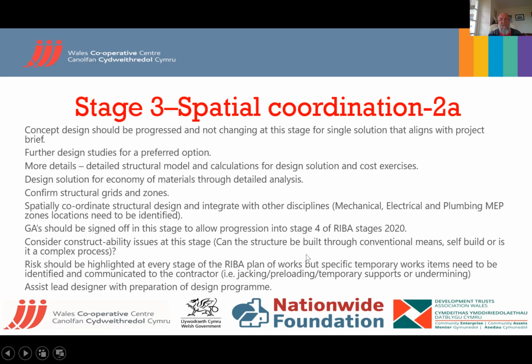Health and safety and risk goes through all stages, particularly if you're doing temporary work. In a trench, you've got to shore the trench up. You will have to get road closures to put services in, connect to the road. If you've got a big crane lifting big timber panels in, that would need a road closure, because you don't want neighbours saying, I can't get in and out, and they'd have to divert the traffic round. So you work all that out in detail.